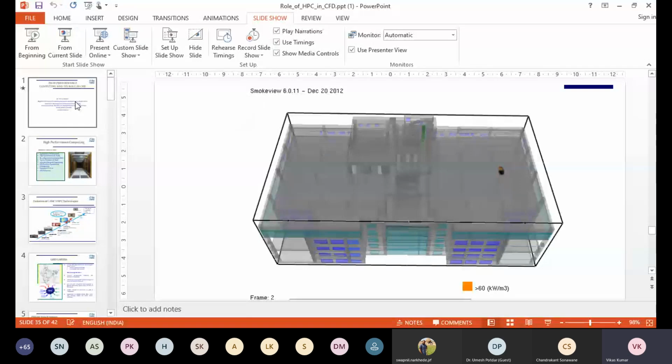Similarly, in solving CFD we use different kinds of linear algebra libraries. Many people are working on these libraries to optimize them so that they take minimum storage and memory and do faster computation. OpenFOAM has standard libraries. We have integrated the PETSc library, and using it, even with the standard OpenFOAM solver, we get 30 to 40% more speed compared to the standard solver available in OpenFOAM.